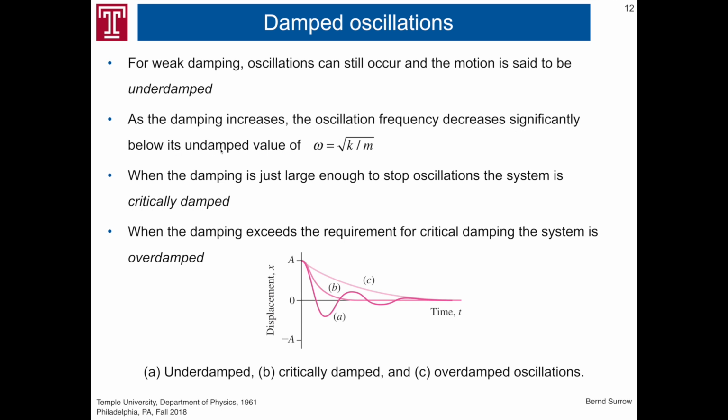And then there's a situation where the amount of damping equals the angular velocity, and we're talking here about the so-called critically damped case, case B. See, you don't have any kind of oscillating behavior anymore. And in case C, one talks about the overdamped case.